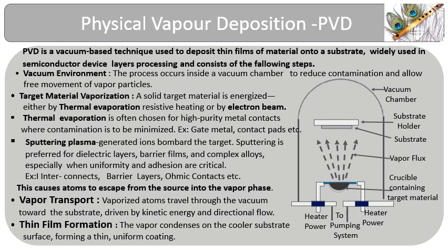Physical vapor deposition is a vacuum-based process used to deposit thin films of material onto a substrate, typically during the metallization phase. The principle of operation is as explained below. The target solid material is placed inside a vacuum chamber. Using either thermal energy or ion bombardment, it is vaporized into atoms. These atoms travel through the vacuum and condense onto the substrate, forming a thin, uniform layer.